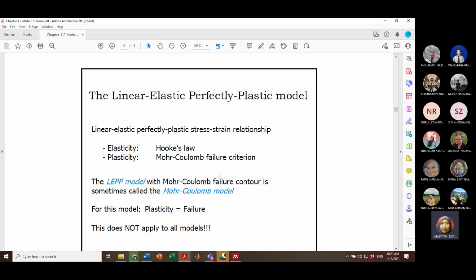At that time you will see the strain, even though our stress is constant, the strain still increases. There it gives you the picture that once it touches the maximum shear stress, no further changes occur in the stress increment, however the strain increases at constant stress.